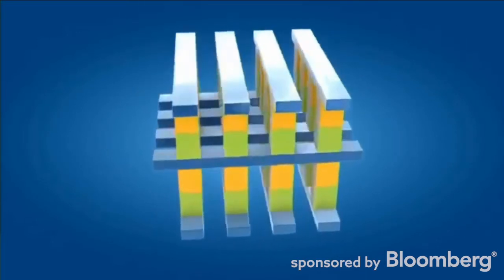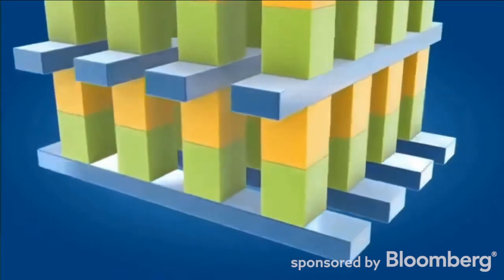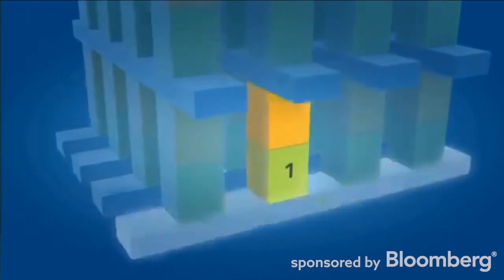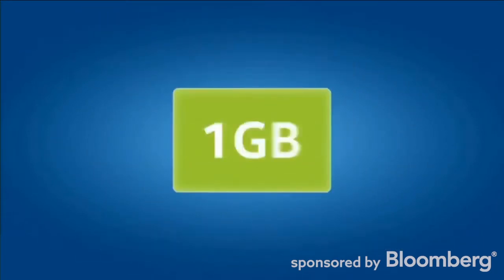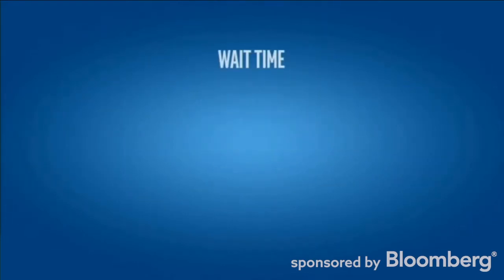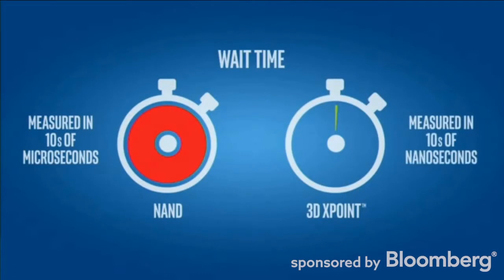And whereas DRAM requires a transistor at each memory cell to access or modify the cell, making DRAM big and expensive, each 3D XPoint memory cell can be written to or read by simply varying the voltage sent to its selector, completely eliminating the need for transistors. This simple, stackable, transistorless design enables 3D XPoint to pack up to 10 times more capacity than DRAM in the same space, greatly reducing cost. When it comes to memory performance, low latency is the key. Whereas NAND latency is measured in tens of microseconds, 3D XPoint technology's latency is measured in tens of nanoseconds, a tiny fraction of NAND's wait time.